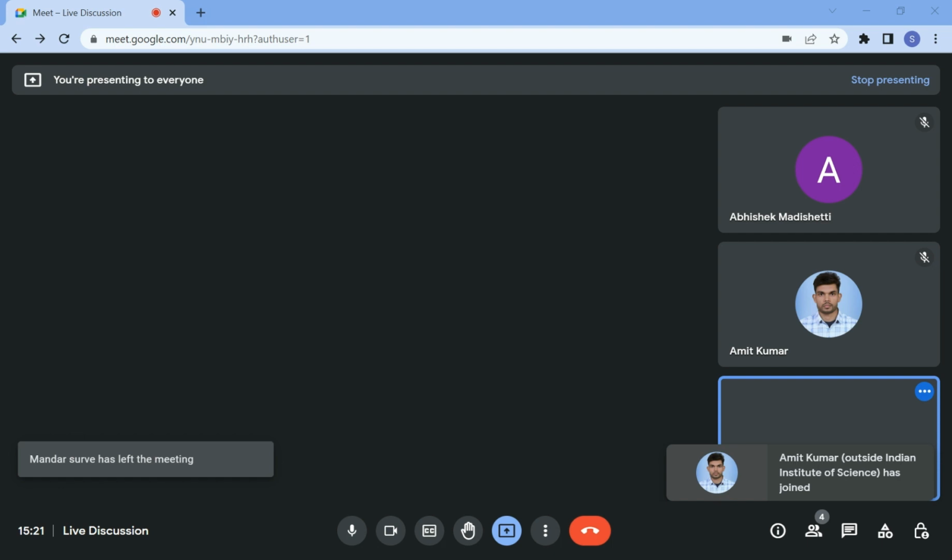This line here, and I projected it here below, and I will be joining this. So this is my AB and this is my AB in top view and front view. So now they have asked find the angle with respect to HP. So now they are asking the true angle with respect to HP. So angle with HP is generally visible in vertical plane. So this 55 is not the true angle.